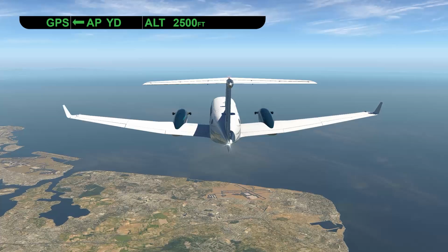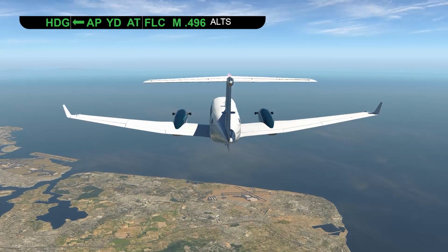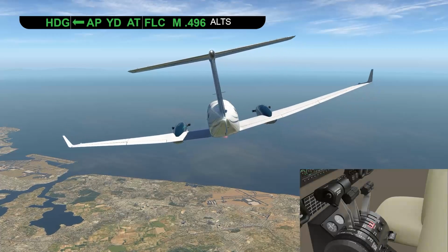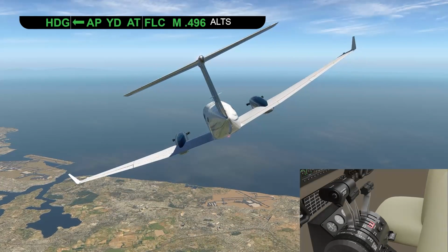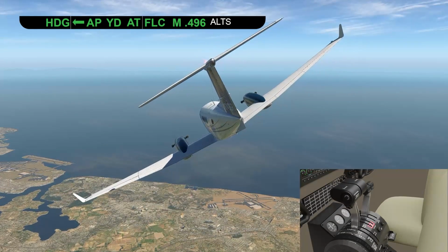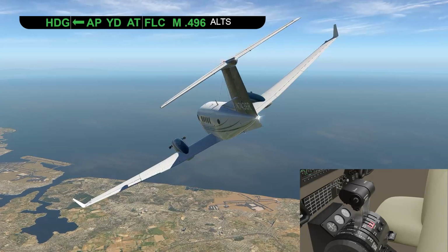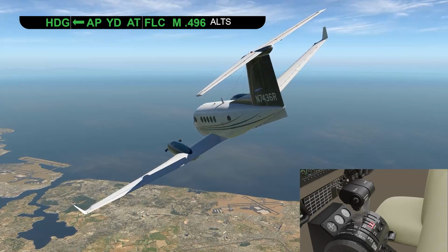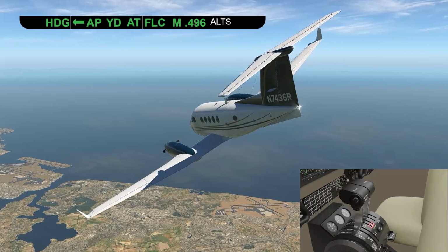When emergency descent mode, or EDM, activates, the autothrottle will engage if not already engaged. It will activate in AT descent and pull the power levers to idle. At level off, it will target the speed selected by the speed selector switch, either the manually selected speed prior to the descent or the FMS cruise speed schedule.